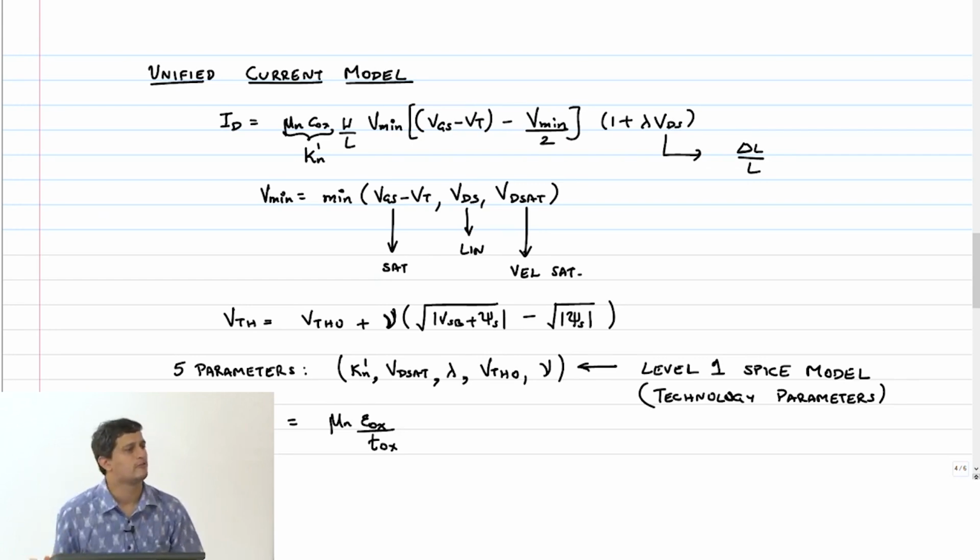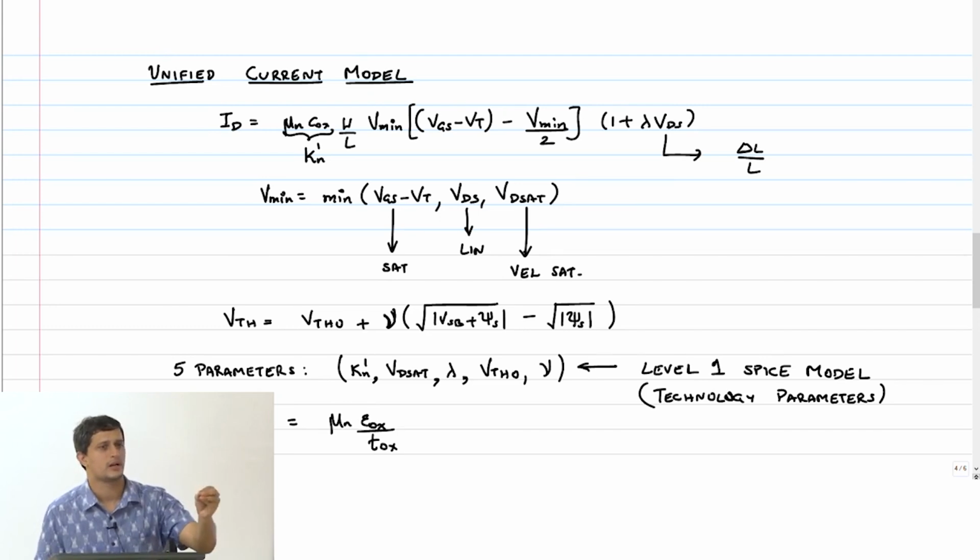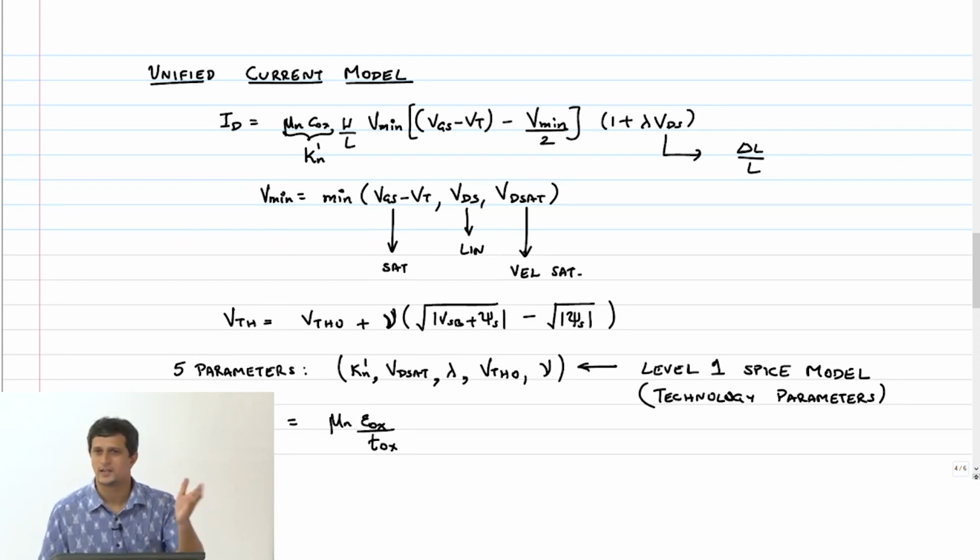Now threshold voltage VTH naught. This again has no dependence on L and W, as you can see in this previous equation or the equations that we derived earlier. It's independent of L and W to a first order, and you get one particular number that the fab says this transistor has a VTH naught of 250 millivolt. It is independent of L and W. But again it doesn't mean that I can take L to 10 nanometer and expect it to give me the right threshold voltage. No, it is for that region of L and W where that is valid.